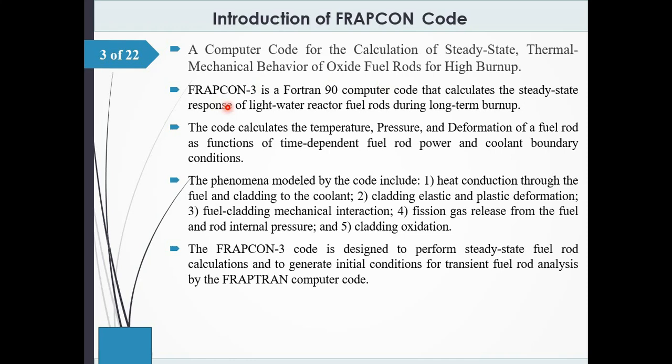FRAPCON 3 is a Fortran 90 computer code that calculates the steady state response of light water reactor fuel rods during long-term burn-up. The code calculates the temperature, pressure, and deformation of a fuel rod as a function of time-dependent fuel rod power and coolant boundary condition.